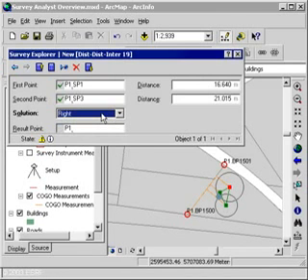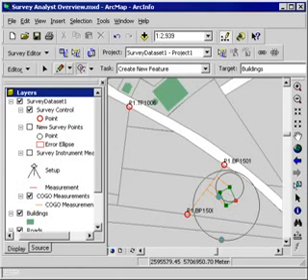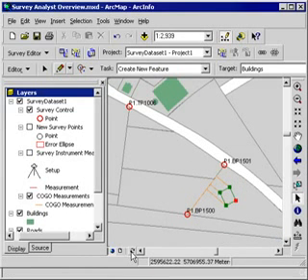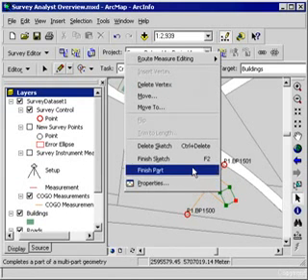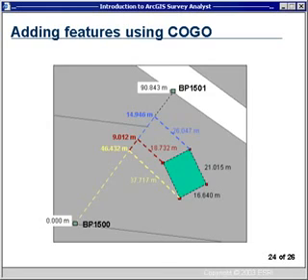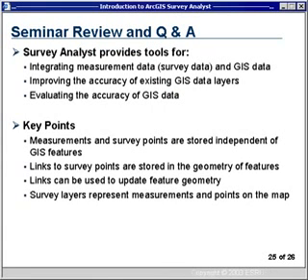I'm going to go back to the Survey Explorer and select the right solution. Once I have done that, you'll notice the other surveyed point is now available. So we've just identified the 4 corners of that building. If I go on to ArcMap and finish the sketch, you will now see that building has been added. And you see the locations of the corners of that building. If I turn off coordinate geometry, you'll actually see the building location. So this concludes the brief demonstration of this technology.